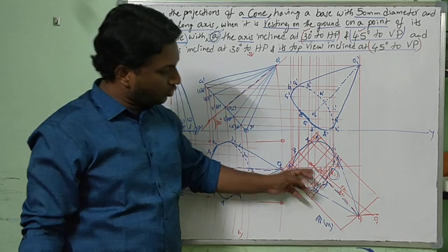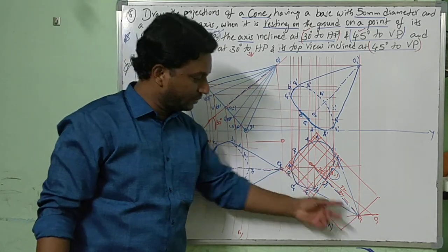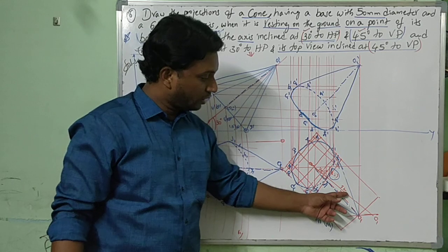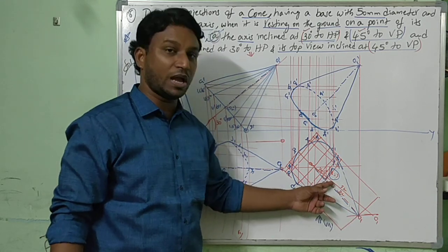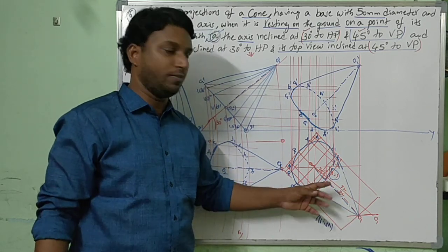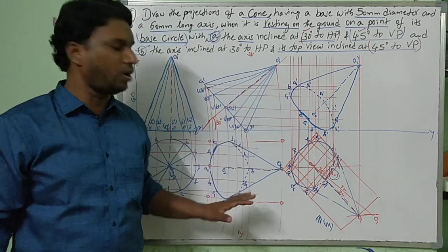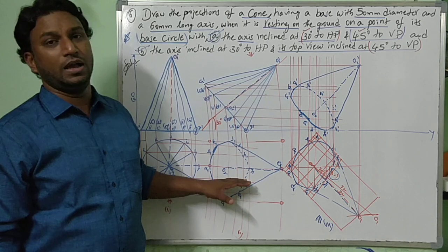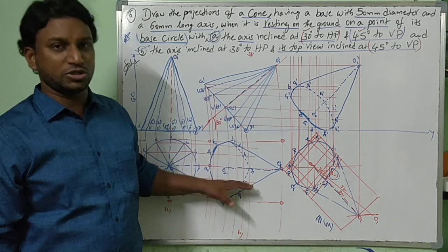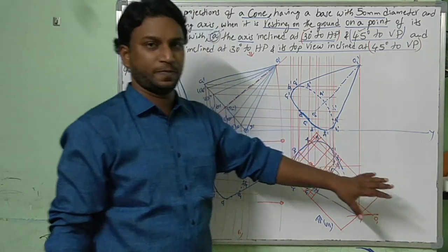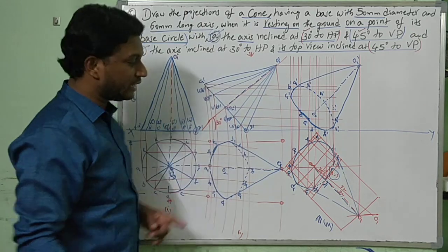But the same O2 O1 line, whatever diminution length we have drawn with the help of true length, we have drawn to find out beta. But here no need to find beta. You can directly draw this particular second stage top view at 45 degrees. Directly 45. But using the length of what?